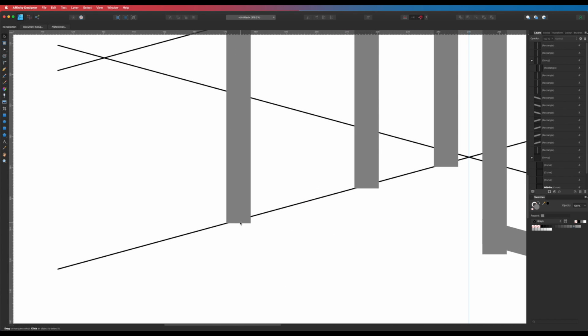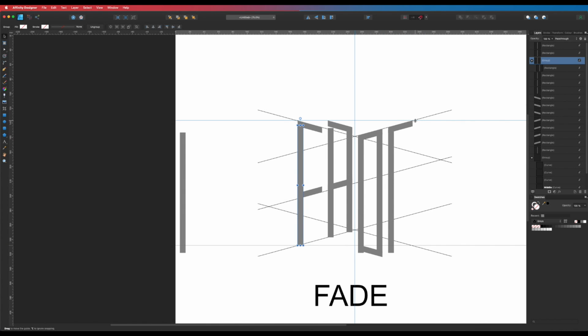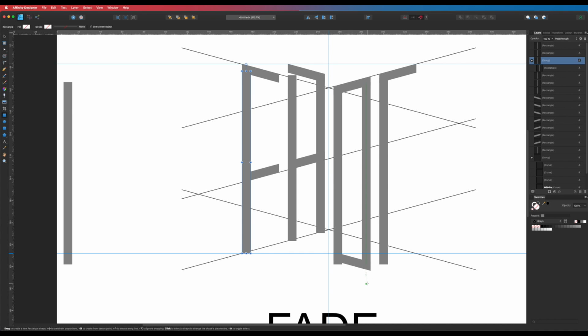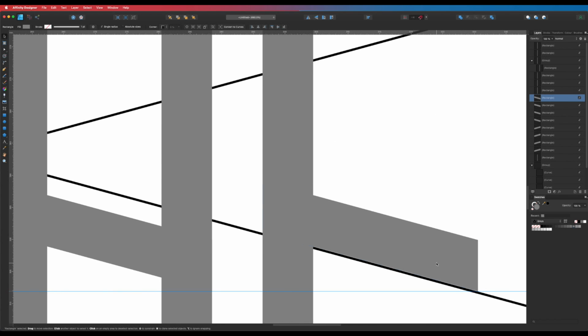What I'm basically looking for is this, where this intersects there, I'm going to drop a ruler. Okay, likewise how we did on this side over here, there's that ruler going across, and that dictates where the line should go on this side over here. So with that said, this should not be scaled smaller. This should be dragged up to about there. Likewise for this line here, which should be right, because that should be dragged and snap right there, which aligns to there. Oh, that worked out really well.